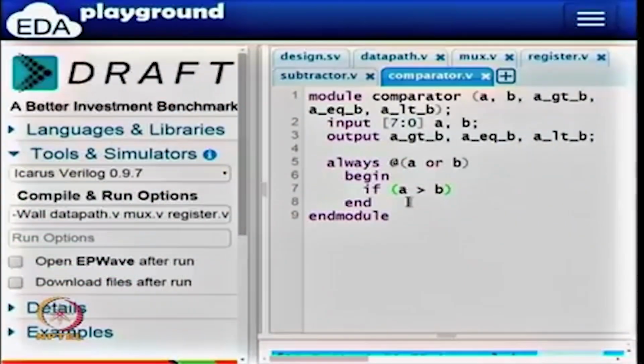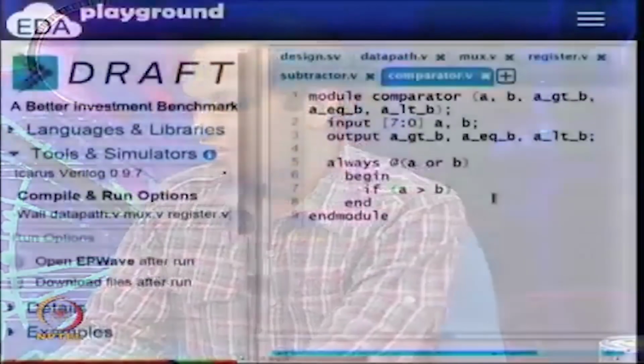So the comparator operator A greater than B means A and B are interpreted as, so these are 8-bit values, right? The 8-bit interpretations of A and B are used directly, and so there are 2 things. When the compiler in the simulator runs, this greater than is a simple operation. You take the 8-bit value and compare with the 8-bit value, but later when we want to infer a circuit for this, the synthesizer will go and look at A greater than B and generate an appropriate circuit for this. So if A is greater than B, then we know that